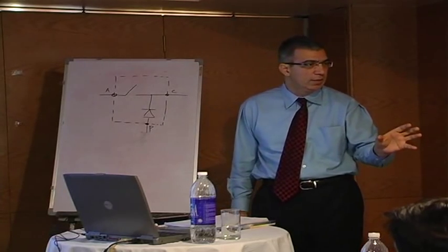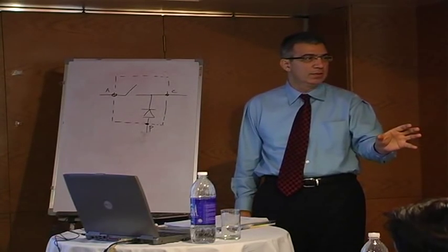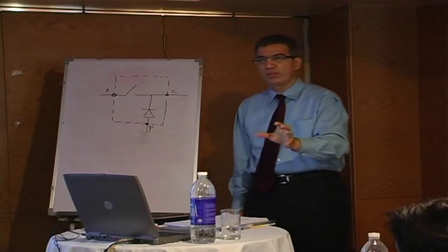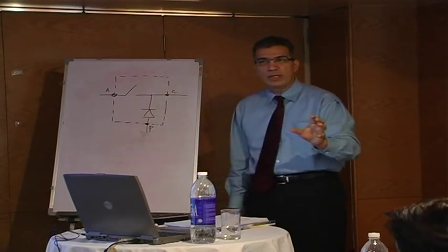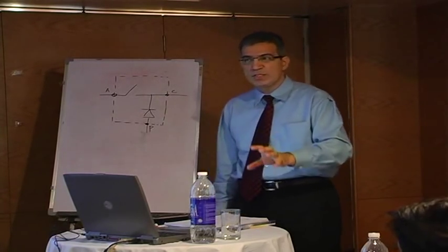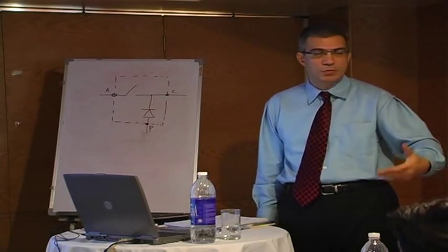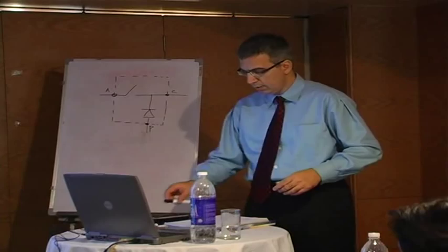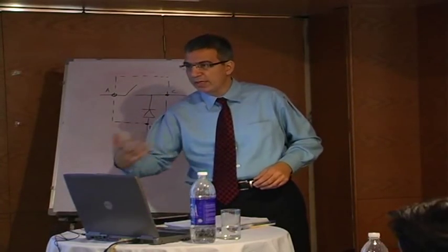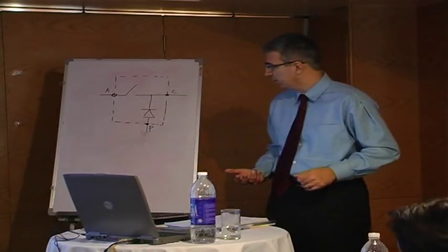All we are interested in is getting that Bode plot, that open loop transfer function of the power supply, so that we can actually compensate the whole power supply before we build it, before we go into the expense of figuring out how to stabilize the power supply.